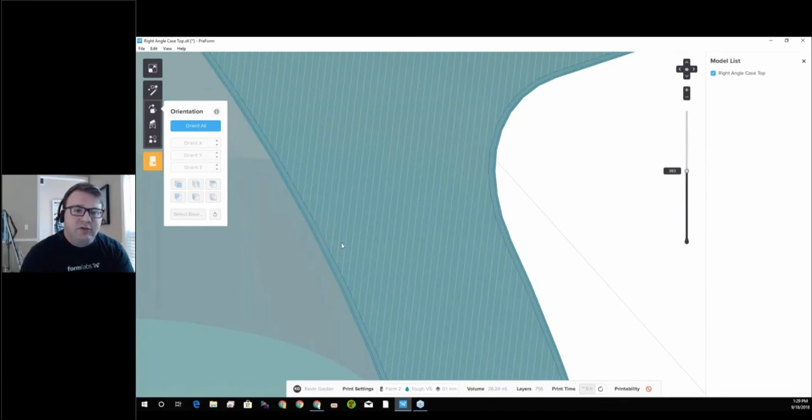So you can see these are the infills, and then we do a couple finishing passes around the outside to make the outside really smooth. And then there's actually one last small step over to just clean up the edge of the part and make it look as good as possible. So the last path the laser will take is this last line here, just to clean up the outside of the part.